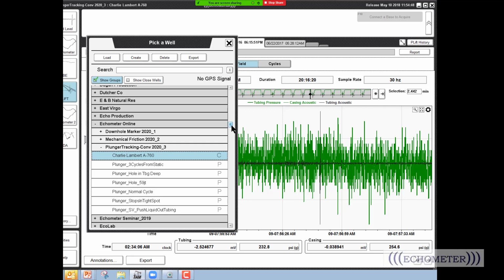The line pressure is dropping because it could be a leak on the outside between the separator and the motor valve. It could be something like that, or maybe you're pulling gas off that line to run something.